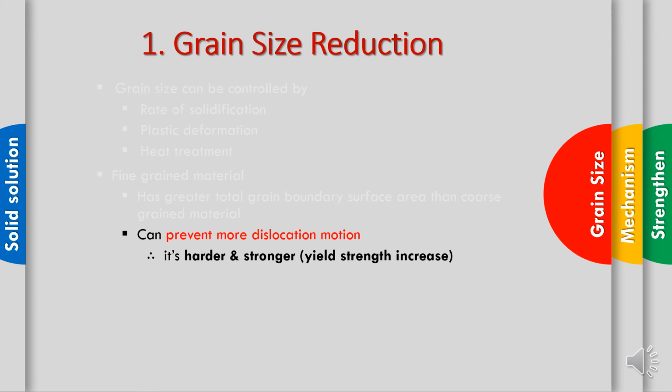It will prevent more dislocation motion, and finally it will produce a harder and stronger material. This is due to the yield strength increase.